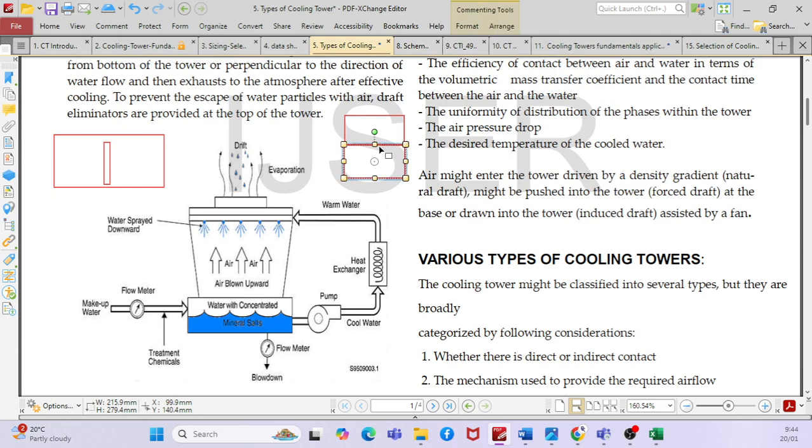Sometimes they will try to combine the two shops into one shop. So when you do the heat load calculation, the airflow rate will be much higher. The design is already done based on a certain capacity and a certain AHU model. So when you do the revised calculation, your AHU flow rate will increase, right? So what will happen? You cannot go with the same AHU, but you also cannot buy a new AHU. Sometimes, if you want to save the cost, what they will do,